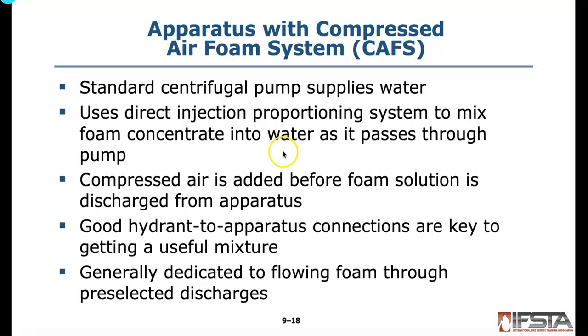Apparatus with compressed air foam systems. These have a standard centrifugal pump that supplies water and use a direct injection proportioning system. What that means is the foam comes in and mixes with water, and it's got the right proportion in order to make the foam.